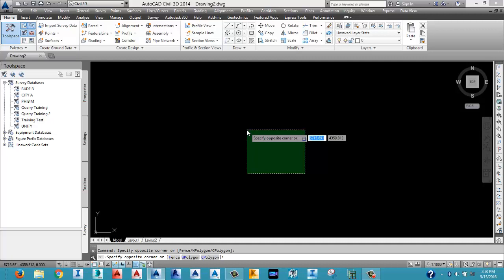Like I always tell people, if you are starting with the software fresh, as a starter or a beginner of the use of these tools, there are basically two ways to bring in our survey data: one, bringing in the points directly as a point file, and two, creating a survey database. So we'll be expecting these two ways of bringing in the survey data.